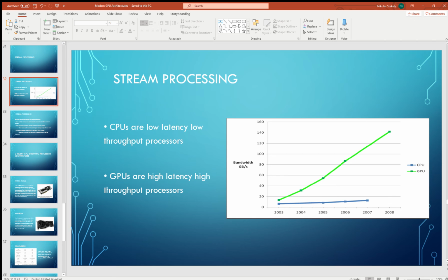The stream processing paradigm simplifies the parallel software and hardware by restricting the parallel computation that can be performed. Given a sequence of data, a series of operations is applied to each element in the stream. Kernel functions are usually pipelined, and optimal local on-chip memory reuse is attempted in order to minimize the loss of bandwidth attributed to external memory interaction. As clearly shown in the graph, bandwidth of GPUs over the years has skyrocketed, whereas CPUs sort of stayed at the same level throughout the 2000s.